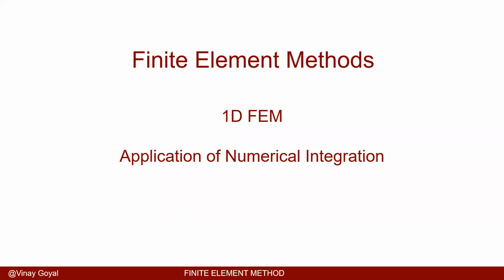Welcome to Finite Element Methods. We'll be discussing the application of numerical integration to 1D finite elements. In the previous lectures, I showed you how we can use Mathematica to integrate probably complicated expressions from -1 to 1. And the Jacobian may be a rational fraction that's multiplied to more complicated expressions and may require complicated integrals. So we need to find a systematic way to apply numerical integration.